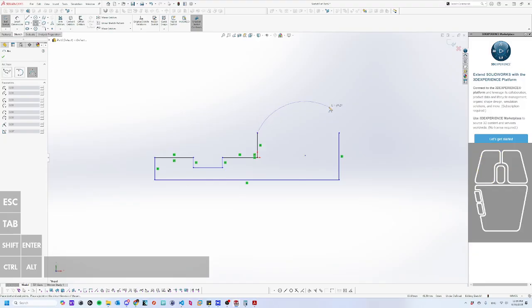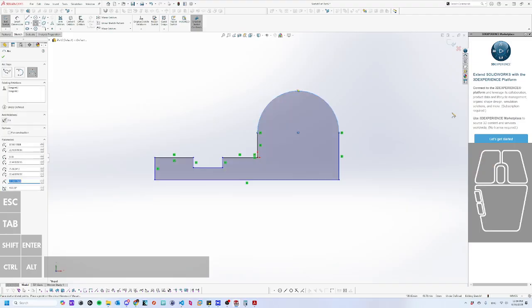I'm going to click on the left point of the arc, I'm going to click on the right point of the arc, and I'm going to click just wherever I want to make the arc. You can see the plus sign that moves along with the arc a little bit below it. That is the center point of your arc. It looks like the center point should be in line with the left side and the right side of the circle. And so I'm going to put the center point where it makes this dotted line and click. This closed my object, and so it's all shaded.